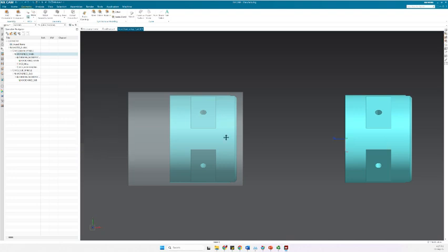All right, now we need to define the same thing on the sub spindle. Again, I repeat, if you have only defined one spindle in your assignment or in your projects, you don't need to follow this step, but in this specific example, we are working with two spindles. So we need to define the workpiece on the sub spindle as well.